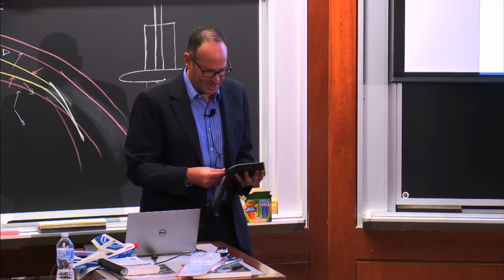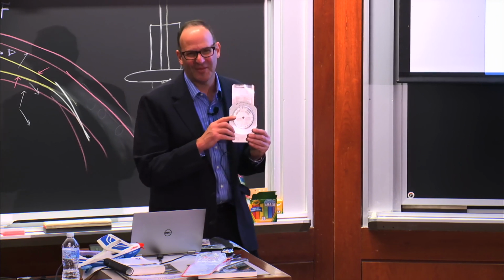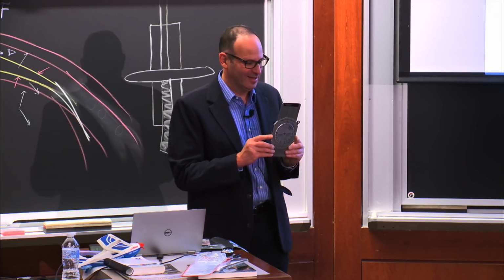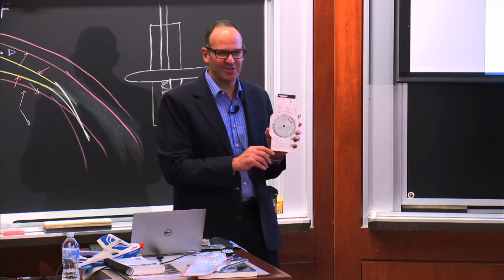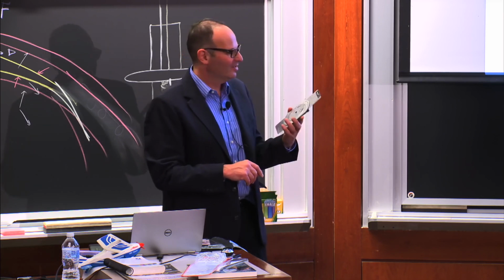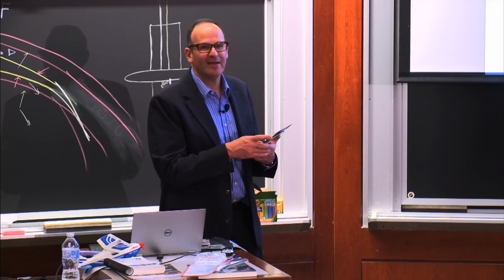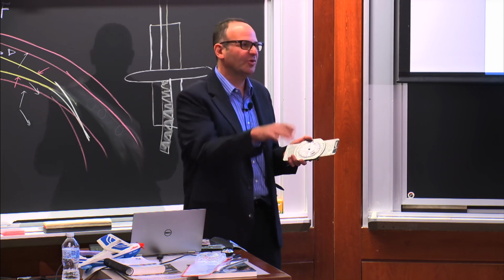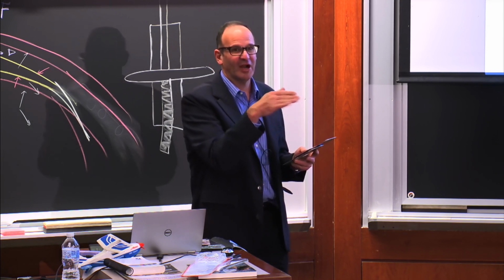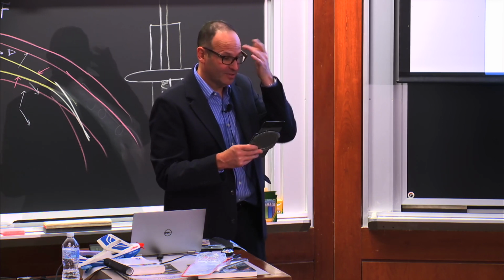This is the E6B flight computer. So I think the E6B designation comes from the US military. I'm not exactly sure when this came out. Probably it says in Wikipedia, but I'm assuming it was a World War II era kind of device. And it lets you make all kinds of computations of density altitude, of how fast you're going truly through the air, as a function of your altitude and what you're seeing on your airspeed indicator.